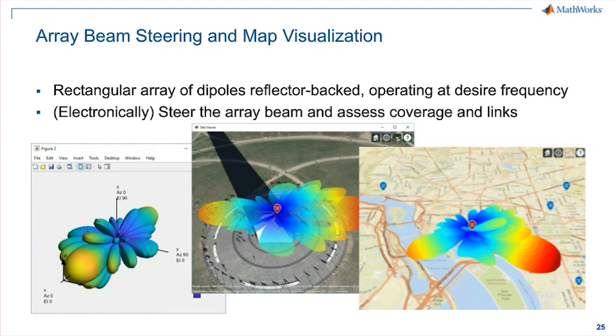Now, when you have it, you can even assume that antenna array is ready to be deployed. Look, here I've taken the famous Washington Monument, right? The obelisk in Washington, D.C. And I put the antenna on top of that. So I know the lat and long of that place, the actual image that MATLAB will show you, and the elevation of that monument. So I created a wonderful multi-directional antenna element array here, and you can actually find the location of your receivers and digitally optimize the transmission such that each of these receivers will be at the highest directivity. So all of that can be done in MATLAB.